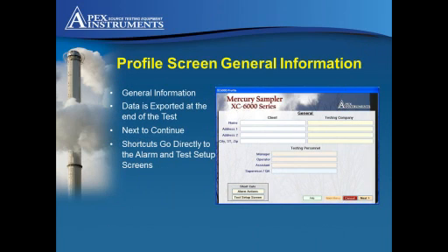The test profile records all of the general information which, once added, doesn't often change, but new profiles are easily added or edited. For example, if the test run duration is changed, or any of the control temperatures or desired flow rate, it's easy to access that profile. What about alarm actions? What happens if an alarm occurs? What do you want the system to do? Stop sampling? Stand by? The profile will contain all of the test run information, the sampling location, the stack details.